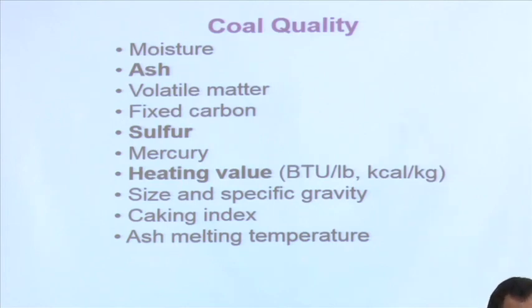First thing is that if you burn it, environmental problems will be there. And suppose that is a coking coal, if you pour it into a blast furnace, the sulfur will degrade the quality of my steel, because of rolling and all these problems. You cannot have sulfur. So, I have to remove that sulfur.